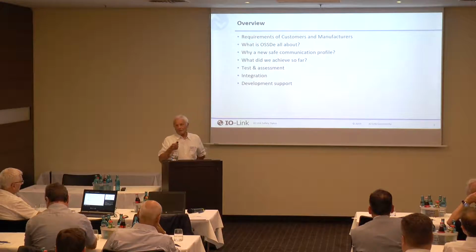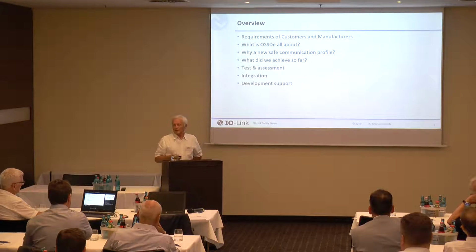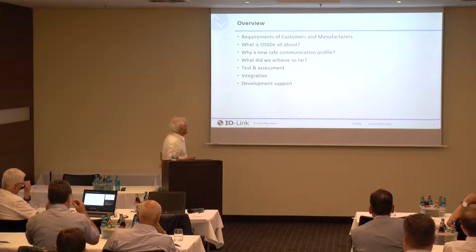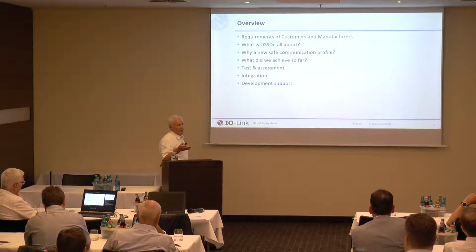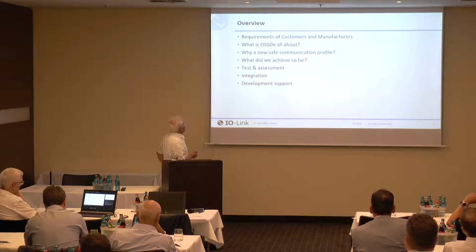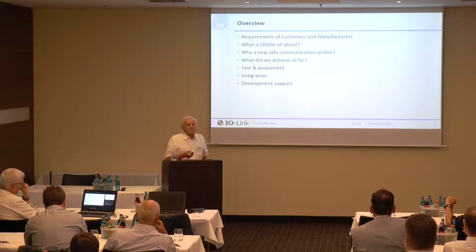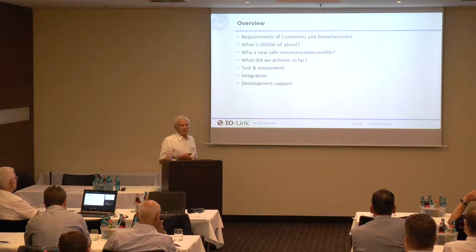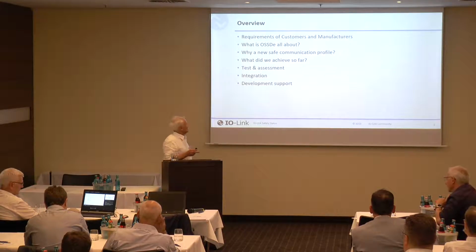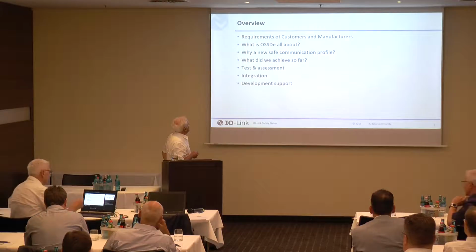We need a transition, like in normal IO-Link, from SIO mode to IO-Link communication. And in our case, a normal input signal is not sufficient. Therefore, in safety, we are talking about OSSD. And I will explain what it is.